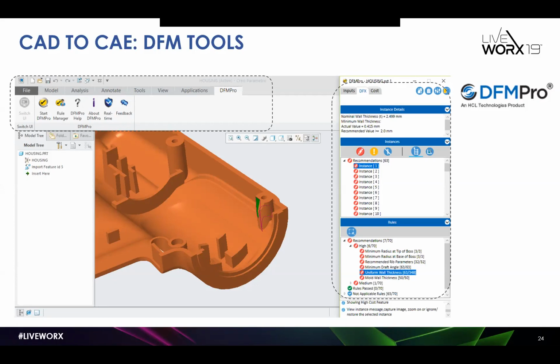It'll tell you whether you're using standard hole diameters and tolerances, if your fillets and rounds are on the correct edges with the correct radii. It'll calculate your edge to diameter ratios, and it'll flag pocket depths that will cause tool chatter, and a host of other checks. You can even create custom checks.